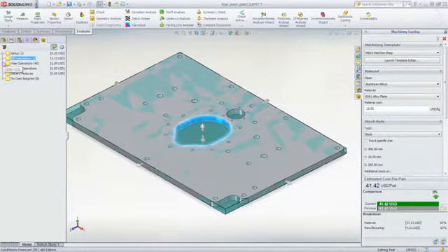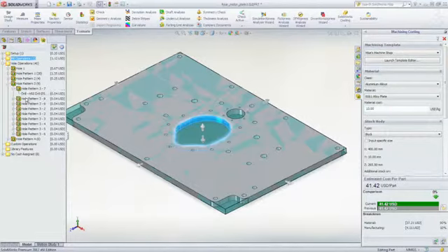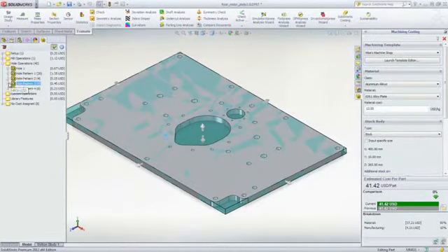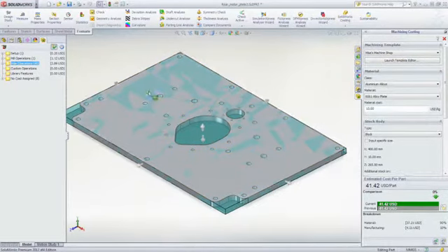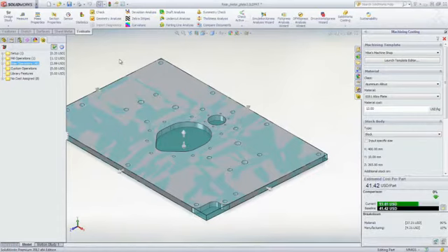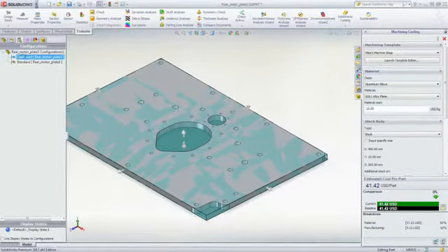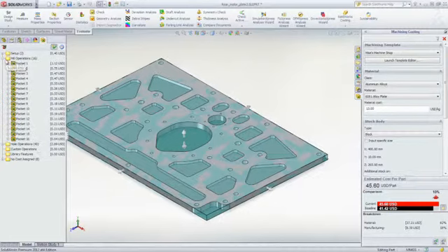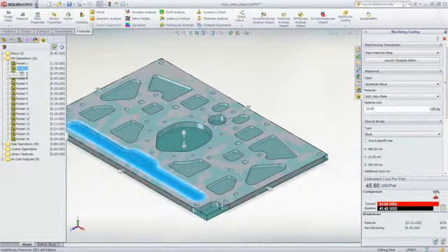There is even the ability to override the type and size of tool used for specific milling and hole operations if desired. As with the sheet metal components, it's easy to compare design changes and immediately see the impact on cost. In this part, we want to evaluate the cost of reducing weight by machining additional pockets. Costing reevaluates the manufacturing operations based on the required tool size, type, and cutting speed to remove the necessary material.